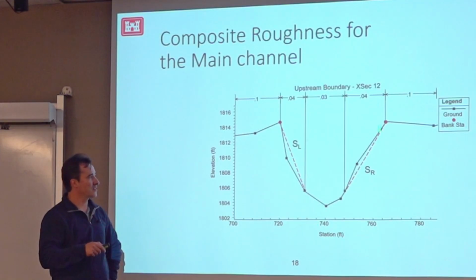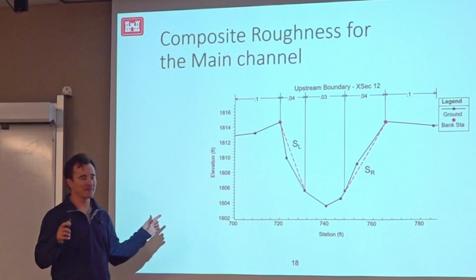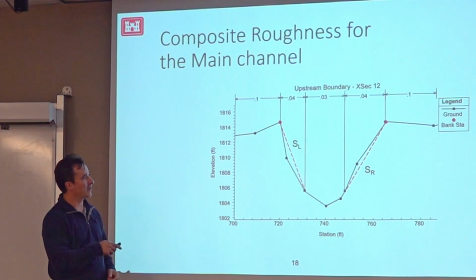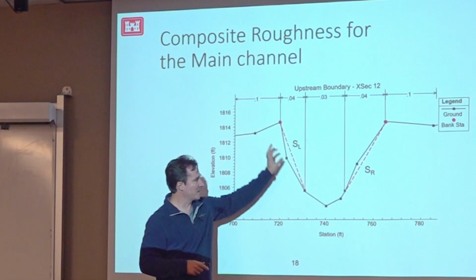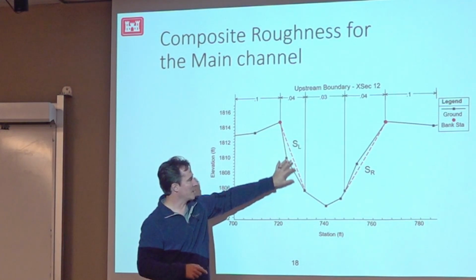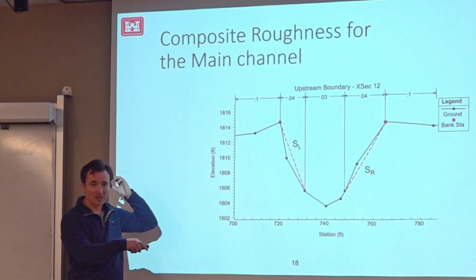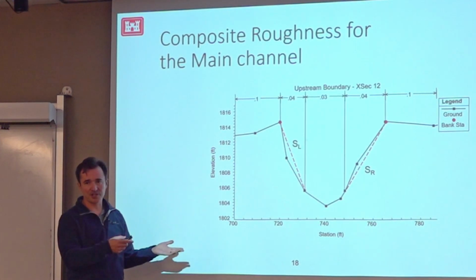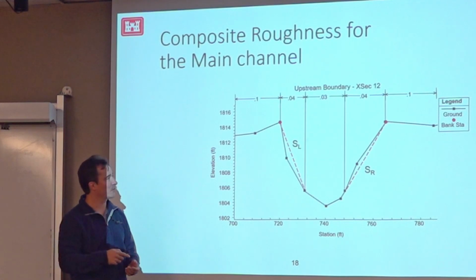Because of the steep banks of the channel, it's better to have a composite Manning's n value for the channel if you have variable roughness along the channel, because if you divided this into sub-bins, the bins on the banks would get a lot of wetted perimeter, and therefore a lot of friction assigned to them. That's not really realistic, right?